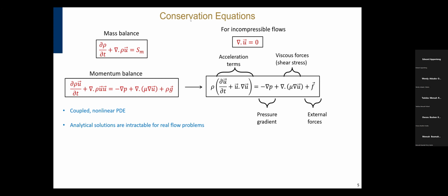Yes. So the answer is, in terms of CFD simulation, most of your time would be spent on the geometry and the meshing stage. You spend about 60% just getting the mesh, and you have to refine your mesh. Now, if you look at the governing equations and discretize them, you end up with a Courant number, which is basically the ratio between your mesh size and your time step. So it's possible that your divergence is coming from having too large of a step size.